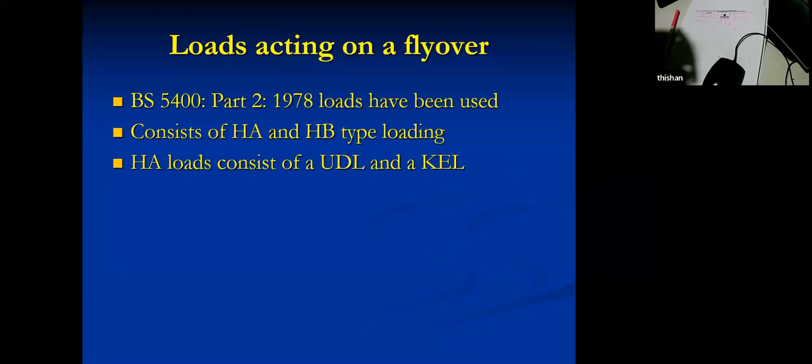And the actual word is QST, quenched and self-tempered bars, where they actually pour water when the metal is red hot. Immediately after making it to the right size, you pour water on it, and that will create a very hard outer crust. But then they will move it, allow it to cool down on its own, because the reinforcement has a soft interior which actually cools down very slowly.